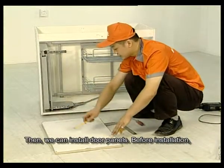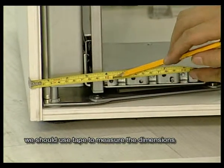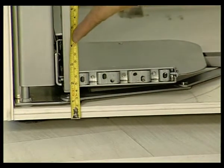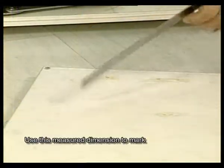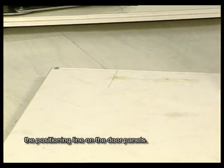Then we can install door panels. Before installation, we should use tape to measure the dimensions of the upper and lower jointers of the door panels. Use this measured dimension to mark the positioning line on the door panels.